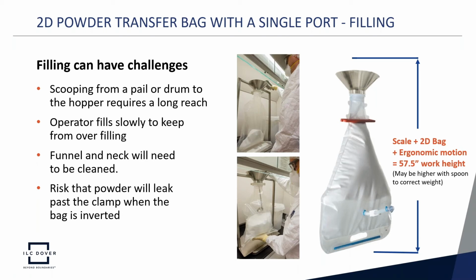So this can be problematic when doing a powder fill, and then also realizing the operator will have to fill into a smaller target, have to be more attentive to accuracy, because as you can see in the picture at the bottom, if the powder bag is overfilled, if the target is missed and the weight needs to be adjusted, that can be a challenge to do. Another tool is needed, a scoop to reach down into the powder bag to scoop some powder out. So this is very important.